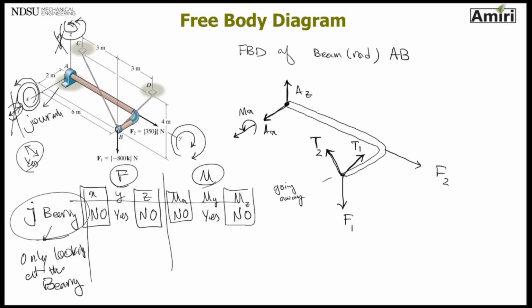MY, does it rotate? Yes, I don't care. MZ, does it rotate? No. So I need to draw an MZ. Again, I'm just drawing all of these in the positive direction. Sorry, I drew that twice. So this is my free body diagram for this problem.